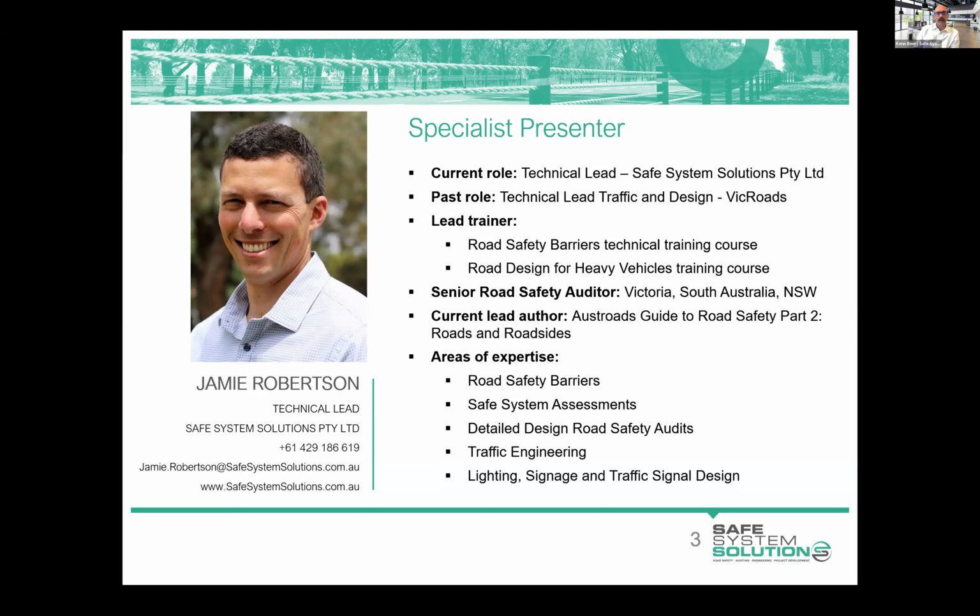I've enjoyed reading a big Austroads report that Jamie had been working on for well over a year now on the treatment of medians on high-speed roads, and how we can get the best safety outcomes with median treatments, with barriers or other treatments, which choice of barrier you use, and offsets, and challenging design scenarios with horizontal and vertical geometry, and all sorts of fun challenges.